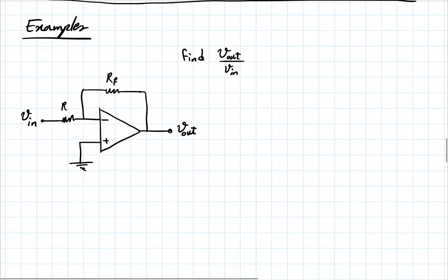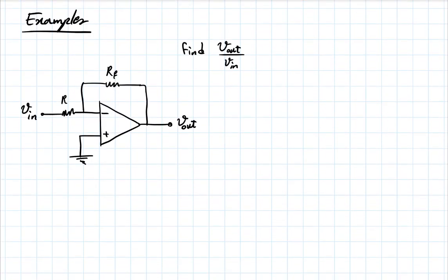And given that we have more experience with circuits, I'd like to do this faster as much as I can, based on things that we know. So if we are going to assume that this is within its linear mode of operation, it's not saturated, and if it's an ideal op-amp, what does that say for the voltage right here? What's that node voltage? 0.